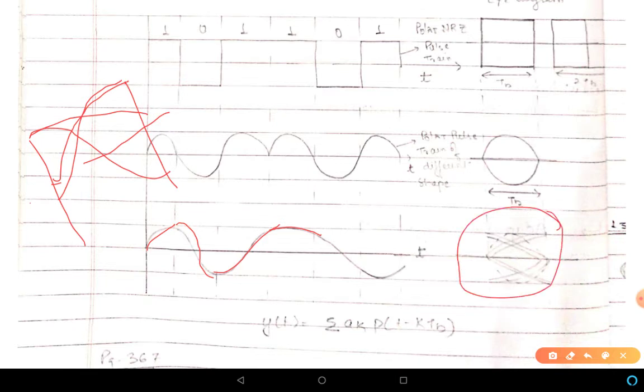It is very clear that if I look at case 1, case 2 and case 3, case 1 and case 2 correspond to channels which are ideal in nature, and case 3 is a dispersive channel, that is, a channel with ISI. You can see that in case 1 and case 2 the eye is wide open, however in case 3 the eye is closing. So one of the important parameters which is clear from this example is that whenever the channel is noisy or dispersive, the eye will tend to close as shown in case 3.